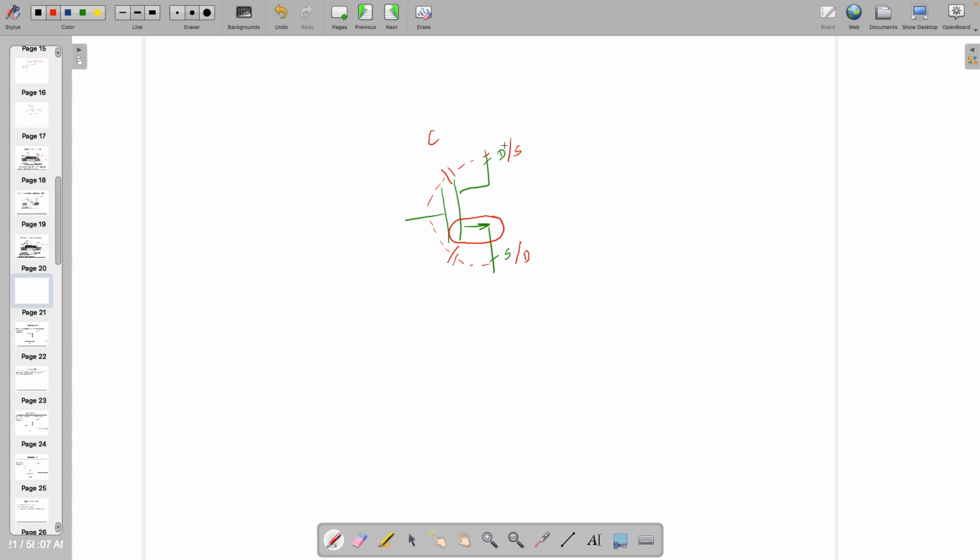Overlap capacitance between gate to drain and gate to source are different. They may not be the same. So model-wise, whatever has been defined is with respect to this source. So it is expected you should not make changes in the schematic like swapping source to drain. That is not okay. It will give you wrong results. However, in layout you can do that. In layout there is no problem.